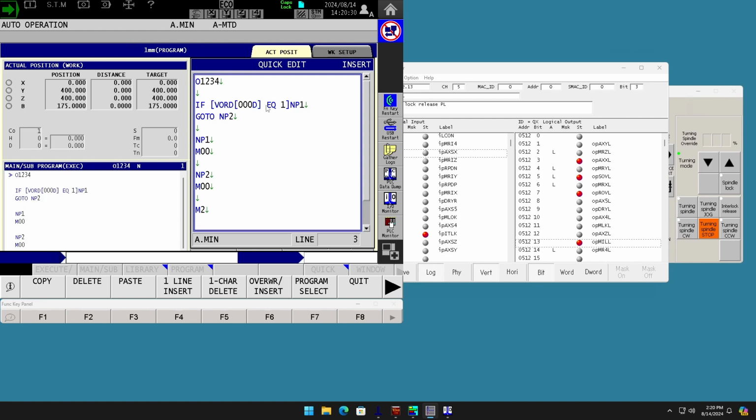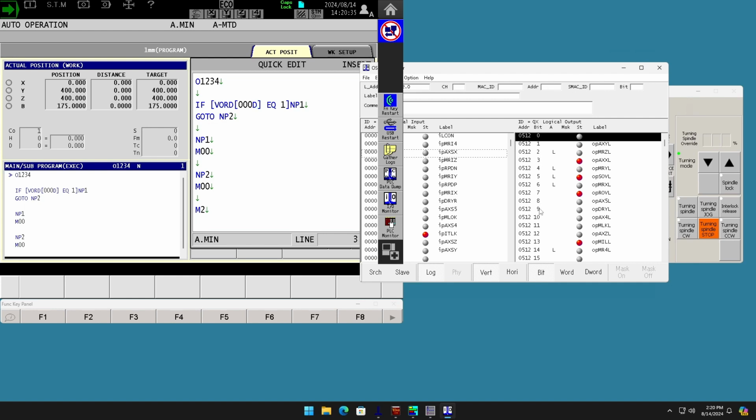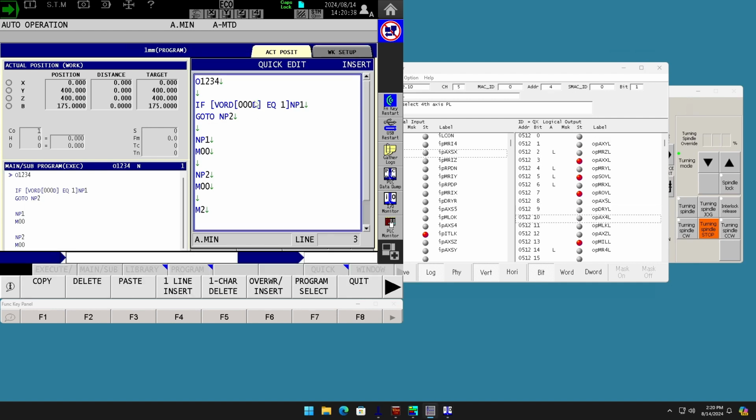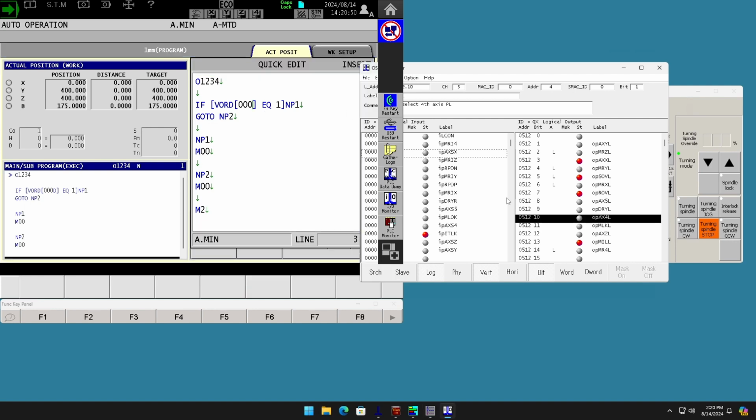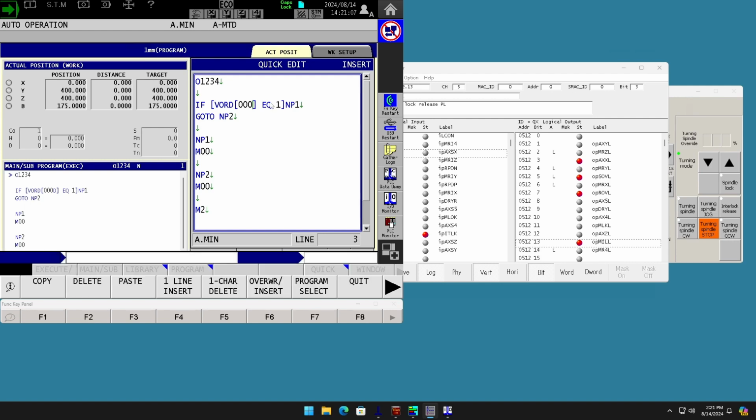The D comes in from hexadecimal. So I run out of numbers here. I can go 0, 1, 2, 3, all the way up to 9, but I cannot put 10 in here. If I do a 10, this will alarm out because it's seeing these leading zeros. It messes the whole thing up. So you're gonna have to figure out the hexadecimal. It's pretty straightforward. 10 is A, 11 is B, 12 is C, 13 is D, 14 is E, and then 15 is F. Since I'm looking at 13, I can just put a D for delta there.